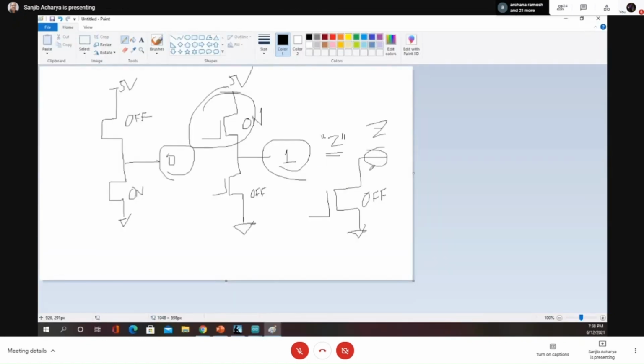So in this case, what you can do is connect a pull-up resistor. Externally you can connect this to 5 volt, and usually it's a 4.7K or 10K, depending on how much current you need. So when the switch is off, instead of high impedance, you will get high, right? And when this transistor turns on, it will pull this down, and you will get low here.